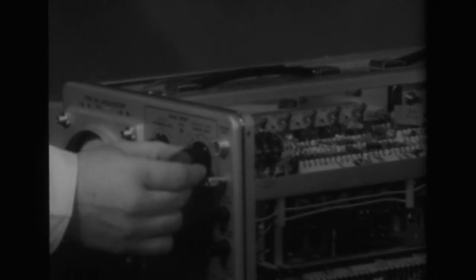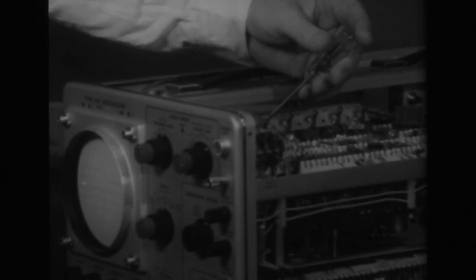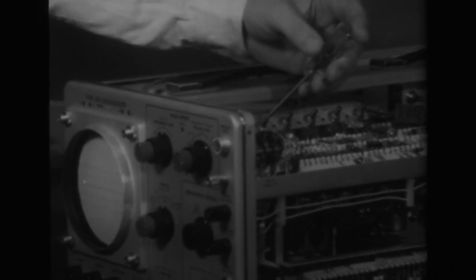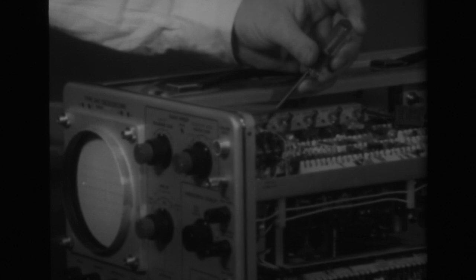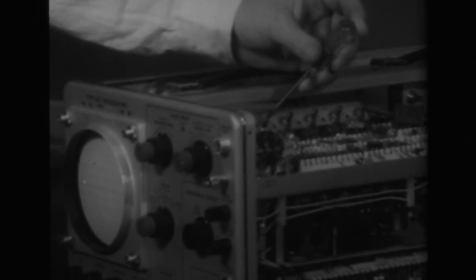Next, with the trigger slope selector switch set on plus external, use a screwdriver and turn the triggering level centering pot clockwise to cock the bistable multivibrator in the trigger circuit, and then very slowly counterclockwise until the sweep produces just one trace across. I doubt that you will be able to see the trace across produced by the sweep generator.